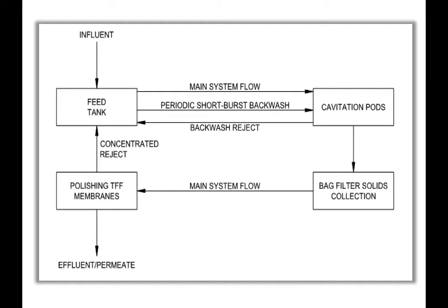So there's two main styles of membrane plants. You have your DFF, which is direct fluid filtration, and you can think of it as a deadhead setup. At those plants that are operating at 500 to 1,000 psi, you're taking the water in and you're trying to recover 99.5% of the water you put into the system. It's a dead end at the end of the membrane, and you are just cramming it through the membranes. You're not giving anything else anywhere to go, any other options, and you're just using overwhelming force, pressure, power, and might to force this water through these membrane pore spaces.